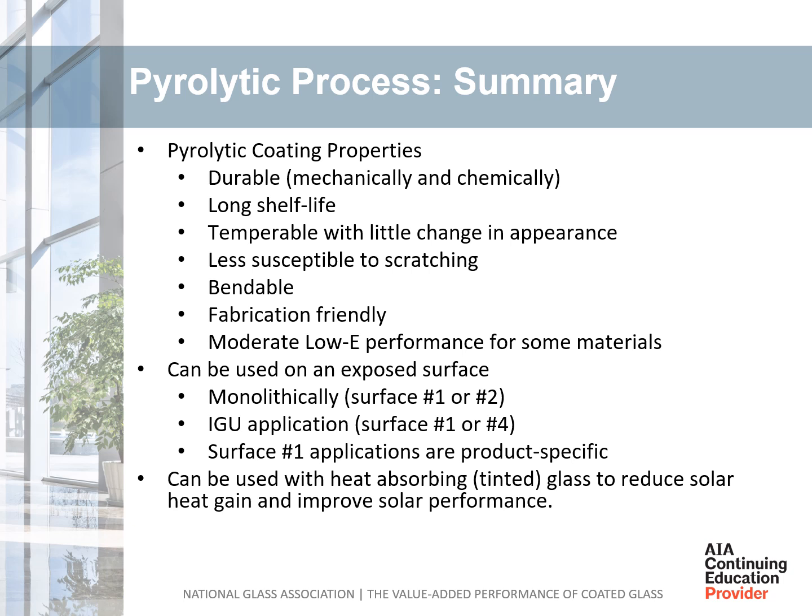To summarize, pyrolytic coatings are known for their durability in a wide range of environments, their shelf life, the ease of tempering with largely unchanged appearance, their scratch resistance during processing, and that they're bendable and largely unaffected during the fabrication processes. They have moderate performance as low-E coatings, which can be used internally or externally in an IGU or on monolithic glass. Finally, they are often used in conjunction with tinted glass to improve solar performance.